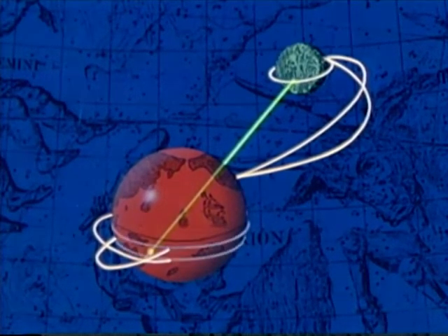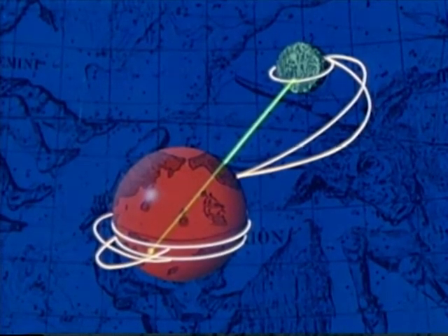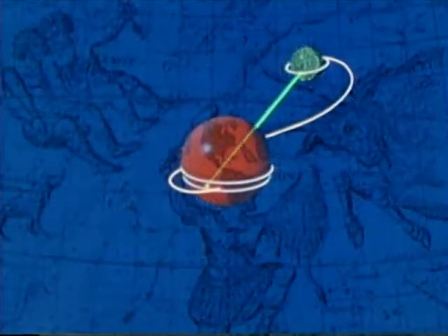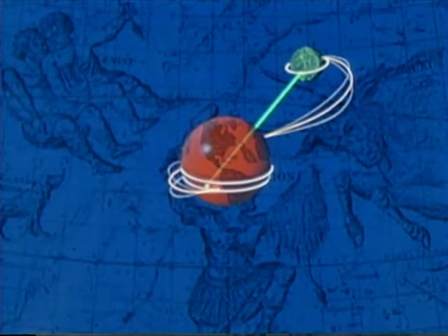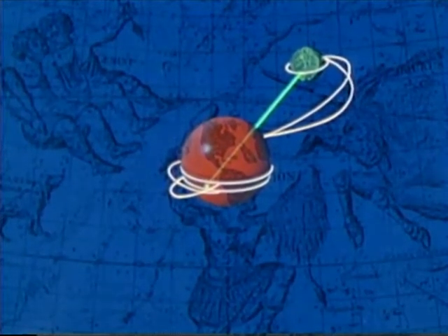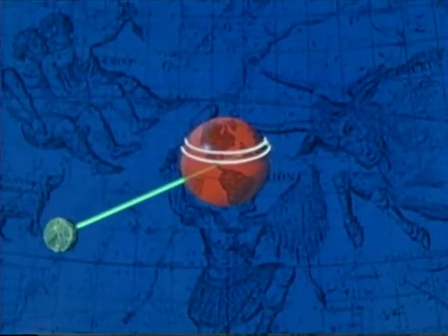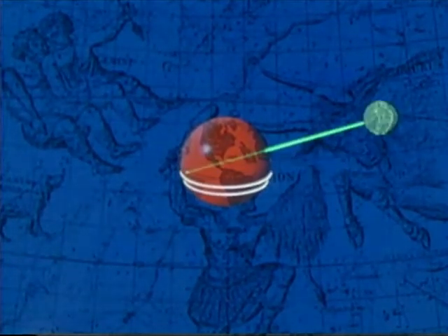Because of the relatively short entry range and thus the small distance from the antipode to the target point, it can be seen that the latitude range is quite small. The landing latitude selected within this range is essentially fixed at time of trans-Earth injection. While latitude range is determined by the possible range of return trajectory planes and the entry range, the location of the latitude range is determined by the declination of the moon. As the moon changes its declination throughout the month, the latitude range shifts accordingly across the surface of the Earth.